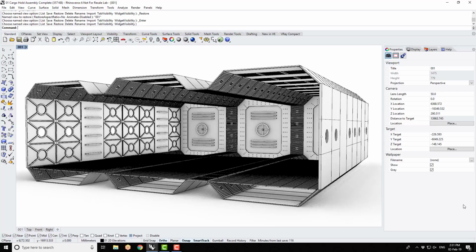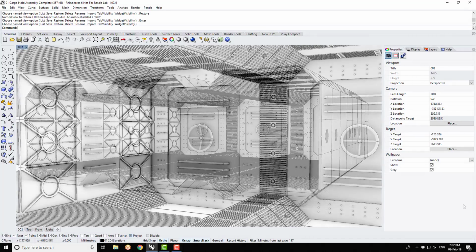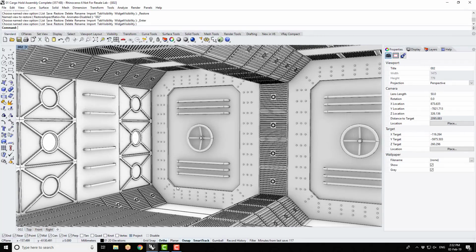One way of understanding blocks is to use the metaphor of components and assemblies. Here, the Rhino file we have open is an assembly that contains a number of components, all of which are referenced block instances. Blocks are especially useful where there are multiple instances of the same component in an assembly, as model and file management can become much easier to control.